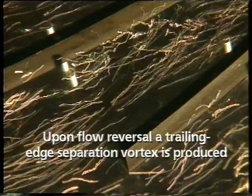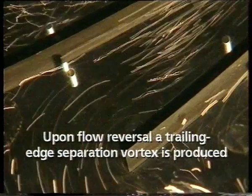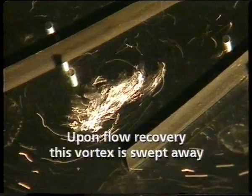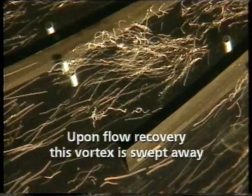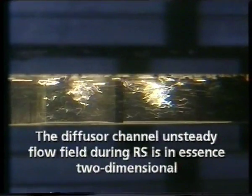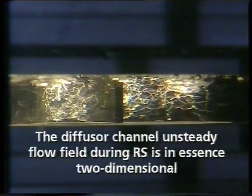Upon flow reversal, a trailing edge separation vortex is produced in each channel. Upon flow recovery, this vortex is swept away towards the discharge. During rotating stall, the diffuser channel flow is, in essence, two-dimensional.